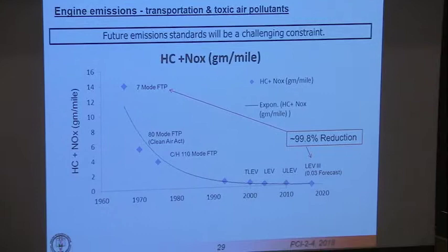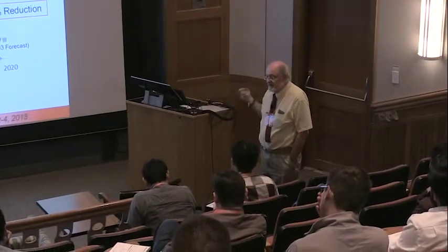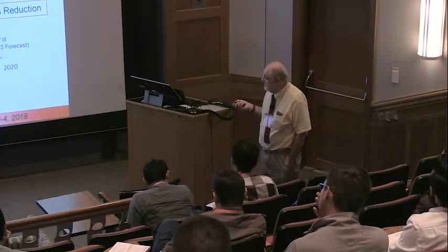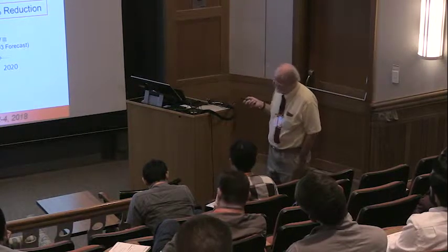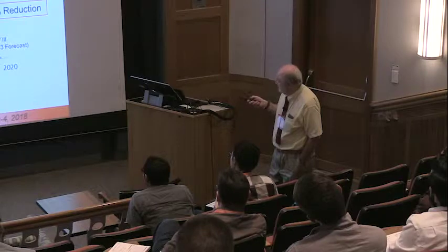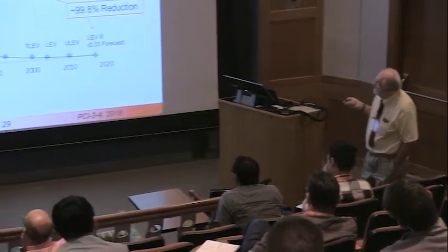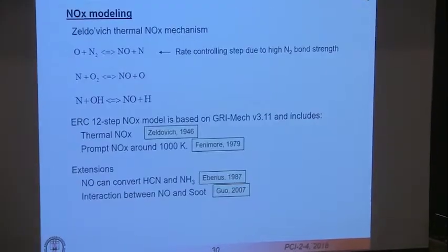It also has to do with very specialized treatments in cold start before the catalyst has a chance to heat up. You want to make sure that the engine is operated in such a way as to minimize HC plus NOx, because a lot of it comes from just the first minute or so of starting the engine. So that's where research really plays a major role in terms of the engine system itself.